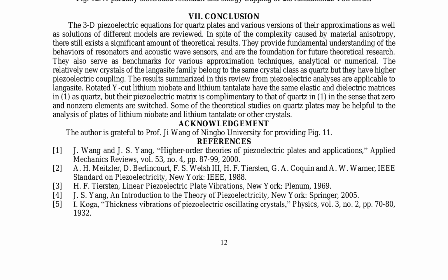The paper highlights several key findings, including the significance of accurately modeling the piezoelectric behavior of quartz plates and the importance of considering the effects of electroding and energy trapping on resonator performance. The comprehensive review of 3D piezoelectric equations and their approximations provides a solid foundation for the analysis and design of resonators and acoustic wave sensors.